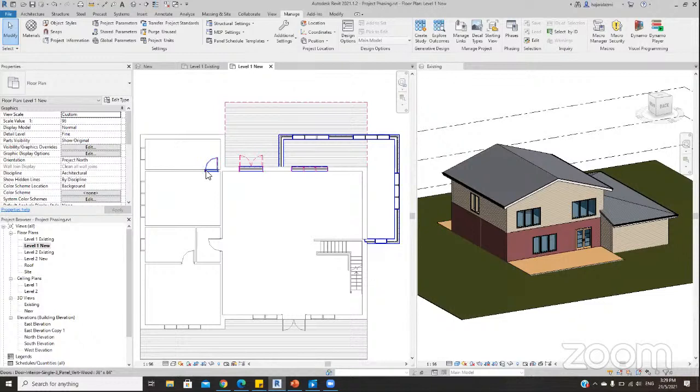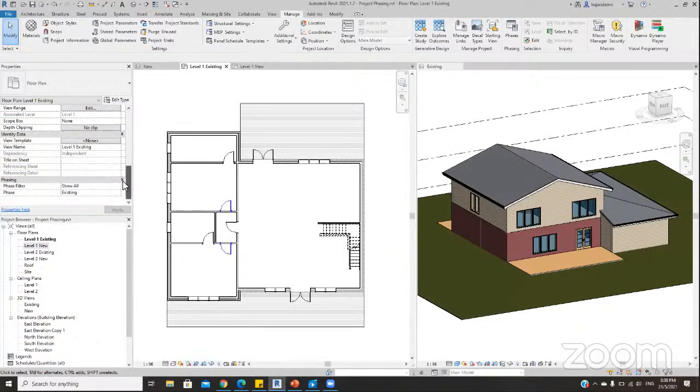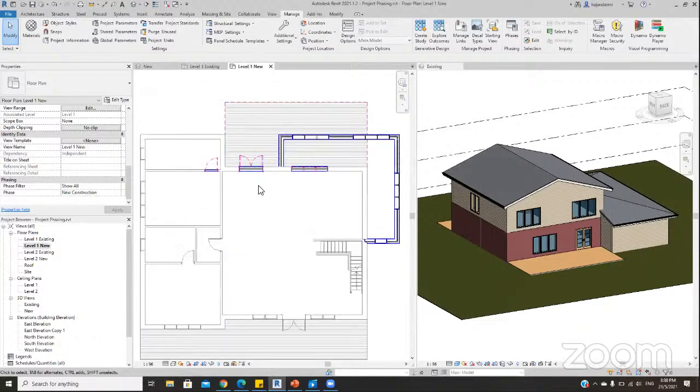The reason why I have the wall over here in blue is because I overrode the setting by category just now. So that's the reason why. Let me conclude again. Whenever you're working in a level and view, ensure that under the Phasing properties, you specify the right phases, so that whenever you make any changes, it will record those activities inside the phase that you have selected.